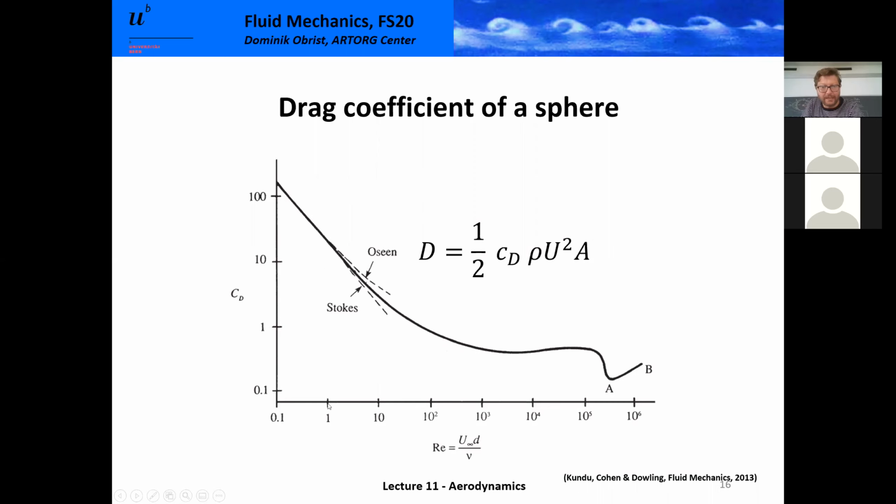Today, we talk about the range where we have small Reynolds numbers. And we're in the Reynolds number range, well, this here, the Stokes Reynolds number range, and up here, the drag coefficient in this Reynolds number range is given by 24 over Reynolds. This line here corresponds to 24 over Reynolds. And you see that for high Reynolds numbers, some more complex things are happening. Here, this dip, this has to do with turbulence, but we'll come to that. But that's the real value of these drag coefficients.